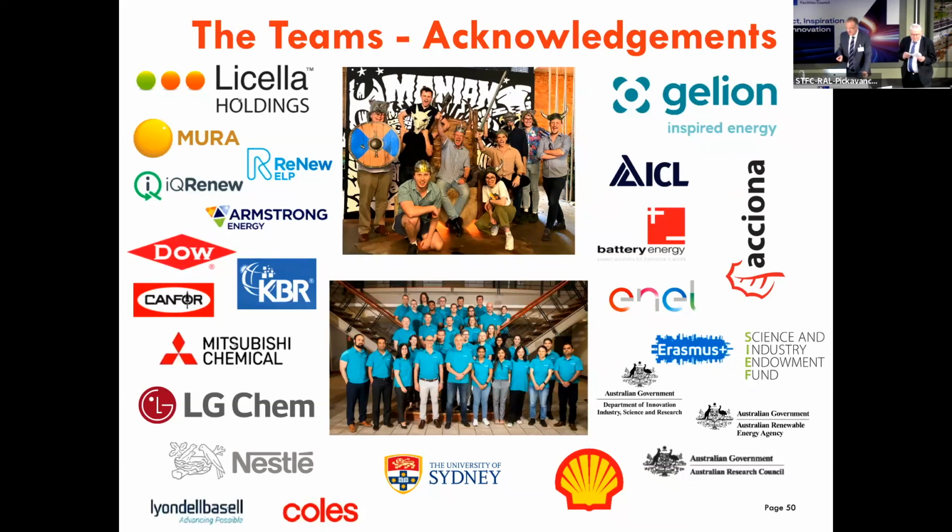The reactor itself is lined with a high performance steel. But when it's not supercritical, we can use lower grades of materials. And because of the way we introduce it, we can make that reactor quite short, and a lot of IP sits there, so I can't tell you. But we have used the same reactor in our demonstration plant for 8 years, and it still looks beautiful on the inside, because from time to time we look down with the endoscope and look at our welds and have them certified because of the pressure. Yeah, and there's a lot of IP in that. If you just go and buy some metal pipes from your local homeware shop, they'll just blow up. So it's a very carefully designed piece of equipment. She'll chat to you in the bar.